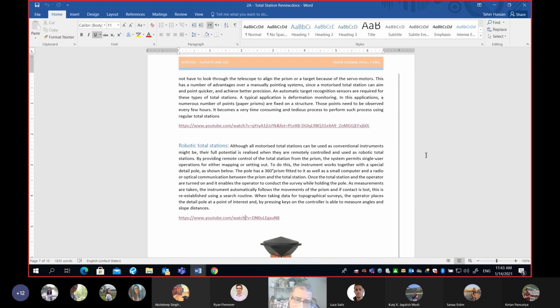When the surveyor arrives at a point of interest, for example, I want to find my coordinate here, like XYZ, the surveyor has a controller, and the controller is attached to the rod. He will say, okay, you know what? I am on top of a manhole, so here is my point description. Survey me now. It is not really continuously getting coordinates. Whenever the surveyor needs, then the total station will record, because there is continuous communication between the surveyor and the total station.